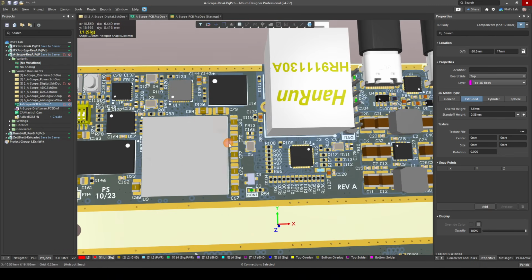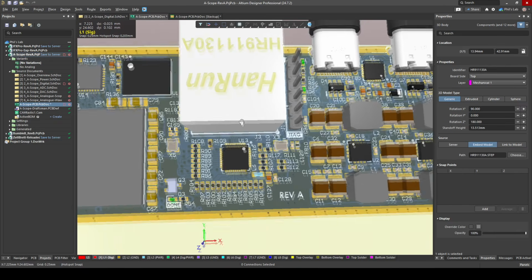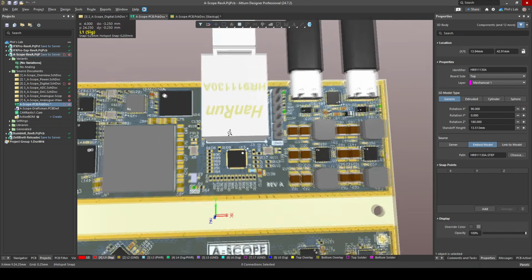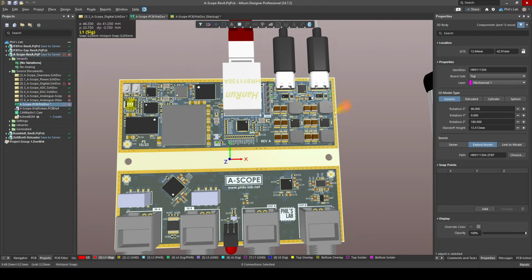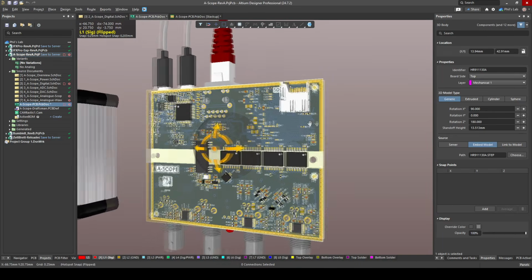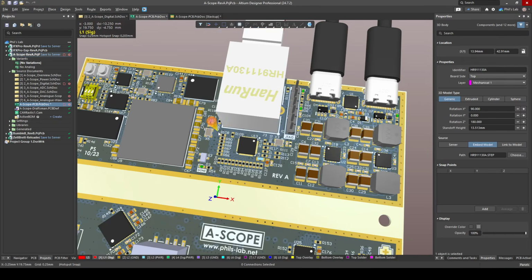We have the system on chip on the left-hand side, which integrates the Gigabit Ethernet MAC. We have the PHY highlighted now in the center, and right above that, we have the RJ45 connector with integrated magnetics, this MagJack. This PCB itself is an 8-layer PCB. It's separated into a digital section at the top and an analog section at the bottom. And this is actually a fully isolated design between digital and analog sections. Of course, now we're just going to be focusing on the Gigabit Ethernet section of this design.